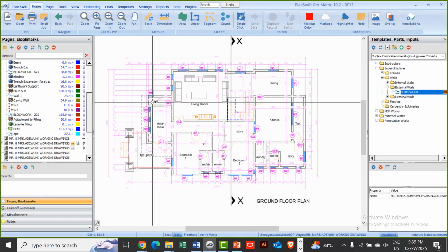In fact, on your superstructure, it's still going to be the same thing that we'll be repeating. You want to measure your block work, which you have measured, and then denote your opening. Then you measure maybe your lintels and your beams. They are concrete work too, right? And there are irons inside. So it's the same process.